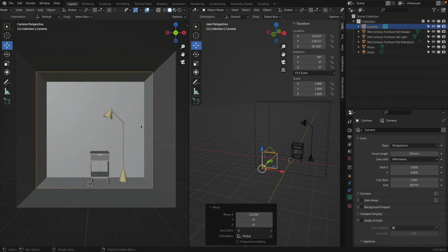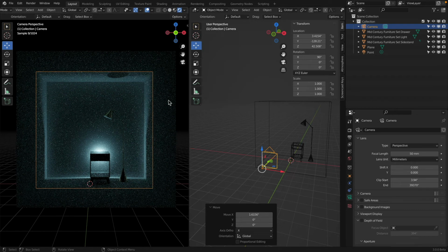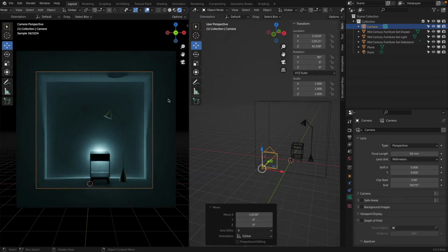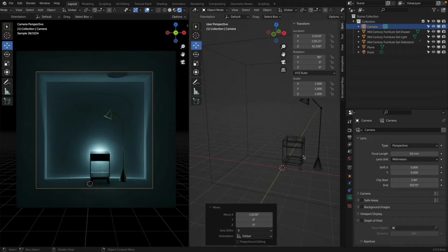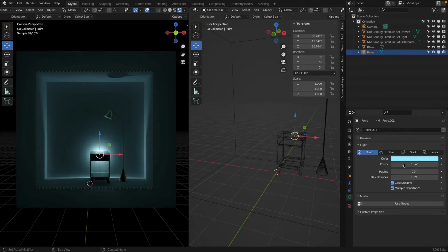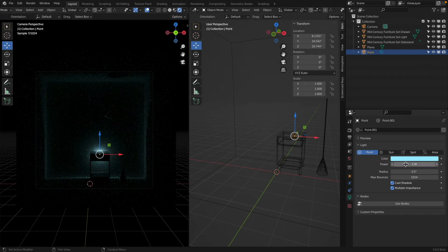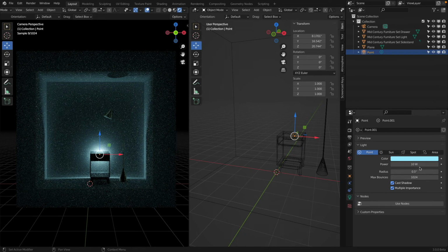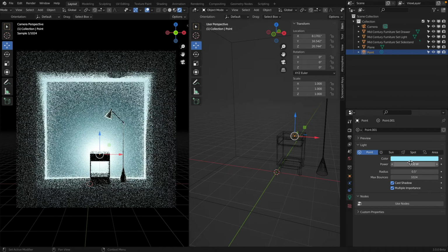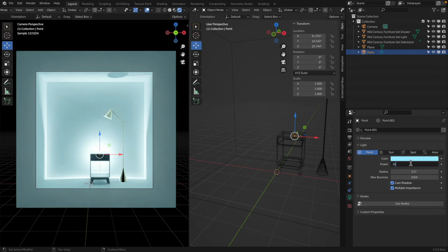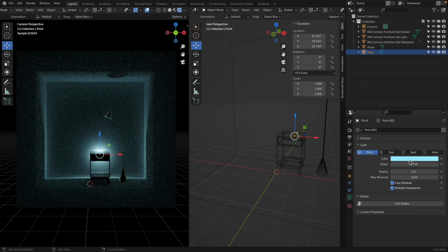I'm centering everything a little bit. Very nice. Let's turn on this rendering. Yeah, this looks actually pretty cool. It's nice and cold. The light is maybe a tick too strong. What about with 2 or 1? It's actually very weak. Let's go back to 10. What about when we set this to 500? It is really bright. Now it's overexposing it. So we have to be mindful of the values here. 10 is kind of cool.